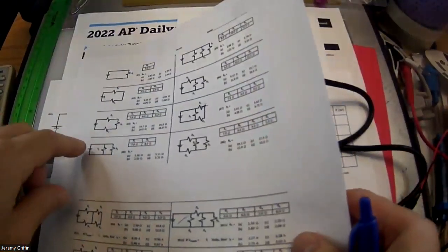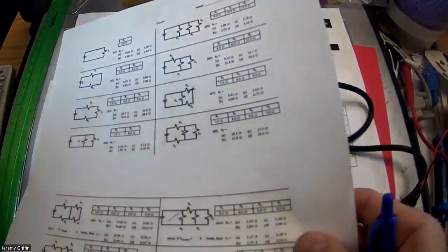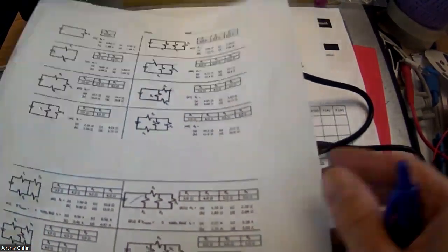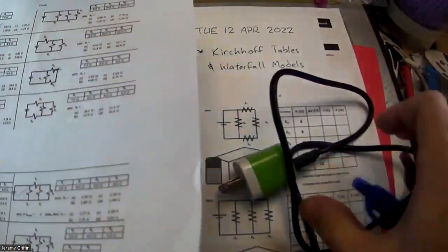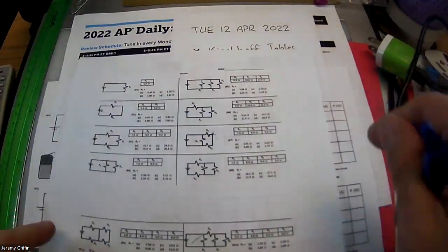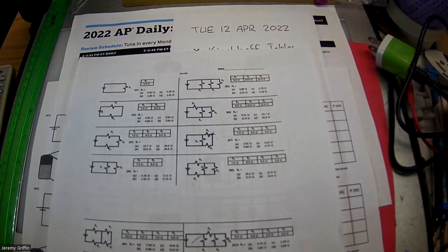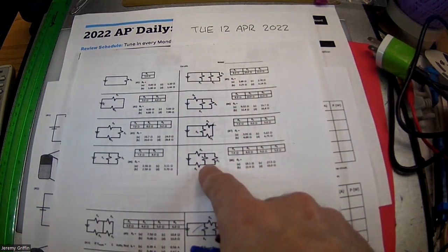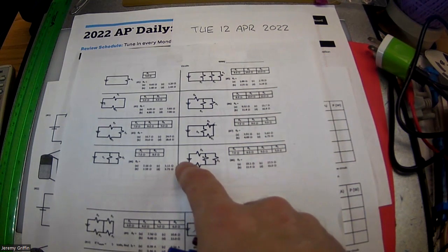You guys remember yesterday we mostly focused on, we did this top 8, we were finding equivalent resistances. From the point of view of the voltage source, the battery, the more resistors you put on in series, the more it increases the total resistance. But if you put them on in parallel, that's like a team that actually decreases the resistance. And then again, these complicated circuits that have some mix, so from the point of view of the battery, what's the equivalent resistance?